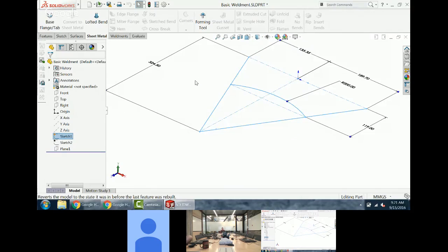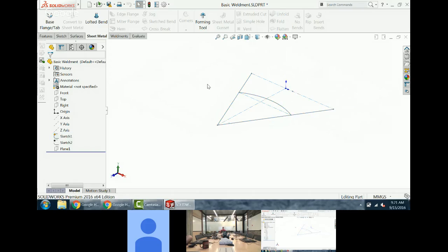You'll notice that it only contains lines and arcs. Those are the only kind of geometry that you can apply weldment structural material to. Like I showed you the hydroplane, I built the rib cage for that thing. That is definitely not arcs inside of that. That is spline geometry because I created it using some complex surfaces. What you can do, I'll show you a little later, is you can make a bunch of arc segments that mimic the spline to get your weldment done when you have complex geometry like that.